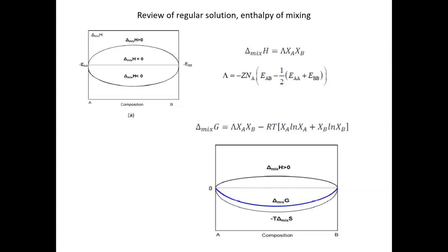Okay, so that's basically the thermodynamic consideration for the spinodal decomposition. Again, we see that this is a scenario when temperature is very high, so the entropy actually dominates the system. When you add up the enthalpy term together with the entropy term, which is very negative, all of the free energies are negative, right? So at very high temperature, the entropy dominates, and you still favor mixing for the system.